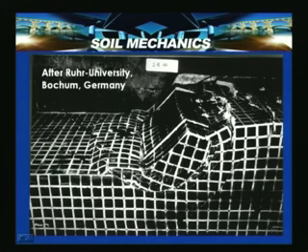And you can see that this portion here is subjected to heaving, and the stretch or extent of these failures can be felt up to this particular portion here. So, this is a physical model which is shown at the end of the test. This is the initial cross section of the slope, and after failure it is at this particular point, and these are the marker grids to enable us to identify the failure surfaces.